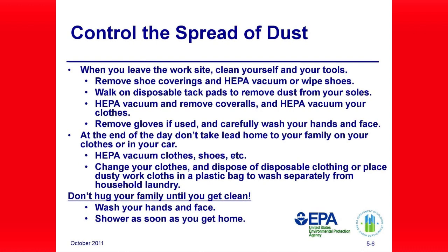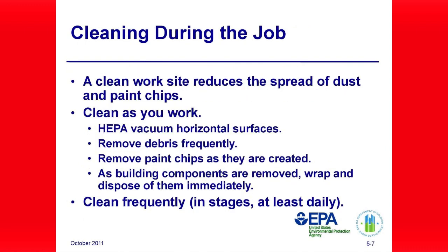Wash your work clothes separately from regular household laundry to stop lead from getting on your other clothes. Be clean before you come in contact with family members, especially children. Remember the video about the contractor who lead poisoned his own kids.